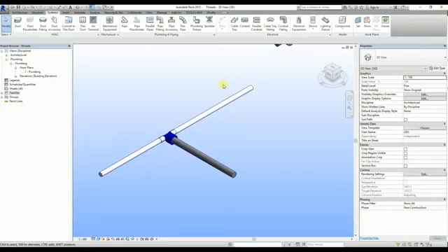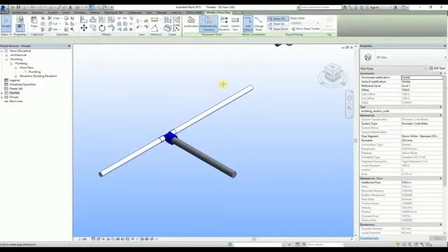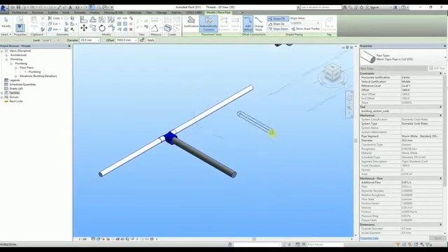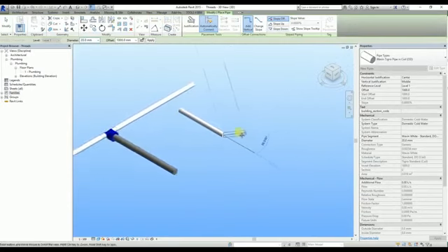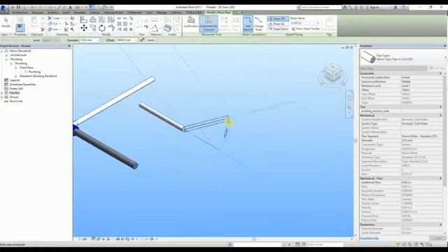Let's try inserting the transitions when drawing a straight line with the pipes. I'm starting with a Tigris pipe, drawing the pipe, and now, without clicking anywhere yet, I'll change the pipe that I draw into sample threaded pipe.